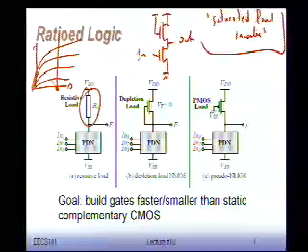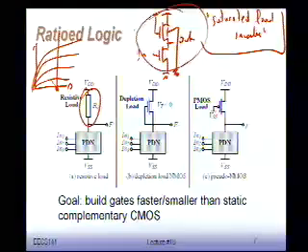Because you can see that this NMOS device is really good at pulling it up. Remember what we said before? NMOSs are very bad at passing a 1. So this thing will try to pull up the output node till it reaches VDD minus VT. At that time, basically the transistor shuts off. So the maximum value at the output is going to be VDD minus VTH. And if we have this thing connected to ground, you're also going to have body effect on it. So the VTH is actually going to be larger than the nominal value. Okay? So not a very good choice.